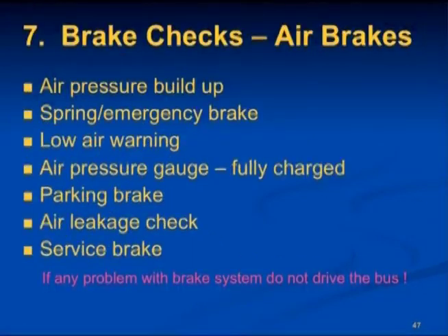Okay, the final thing to be checked before you do your documentation and roll out on the road are the brakes. The brakes can be either air brakes or hydraulic brakes. So let's talk about the brake checks first for air brakes. If they're equipped with air brakes, check the anti-lock braking system and indicator lights. The lights should come on and then turn off.